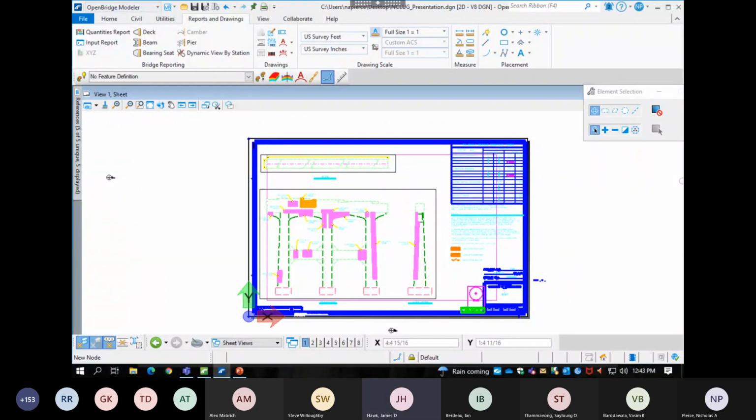We have had trouble getting an accurate shape for end-bent caps in the 3D model. The digital twin will have the right general shape, but beam seats and bottom of cap slopes are difficult to customize, and elevations would not be accurate to the inch or fraction of. Would that be close enough for phase 2?